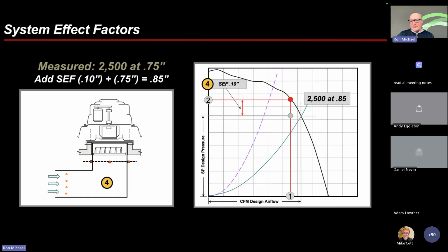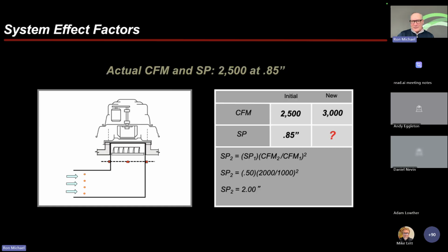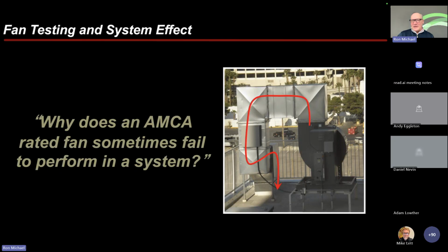So air balance reports are obviously always required. The biggest misunderstanding with air balance reports is they don't tell us exactly what the inlet conditions and outlet conditions were like and where they measured from. As long as they do that, we can usually go in and solve the problem. So this is what you run into again from time to time.